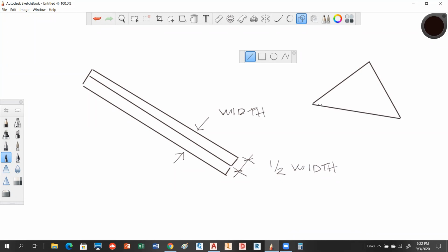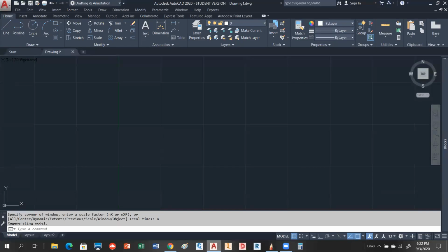Now, in AutoCAD polyline terminology, you can either have it open or closed, and it can still look like it's closed, such as this, but it won't be unless you use the close option. Then it'll be a true closed polyline. So if we have width on this polyline, we're going to be able to see that. So let's go back here and take a look at this.